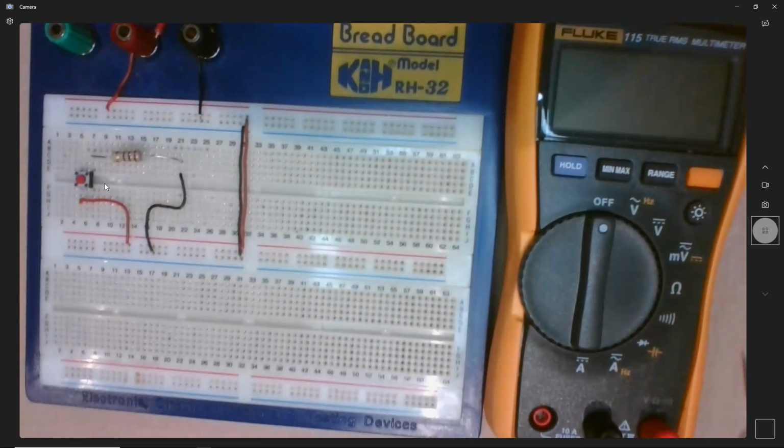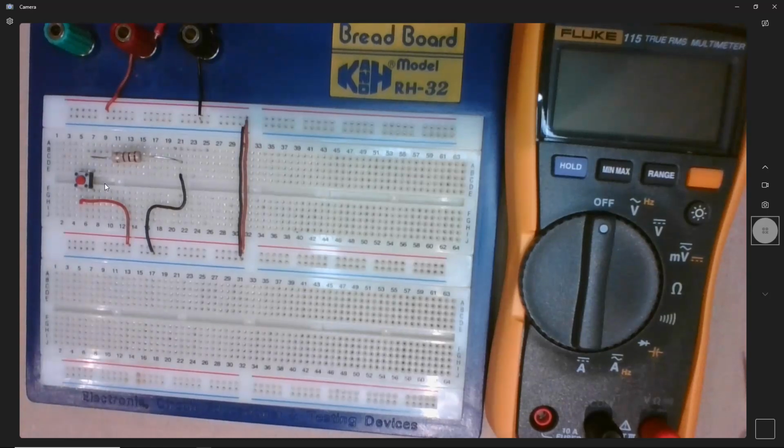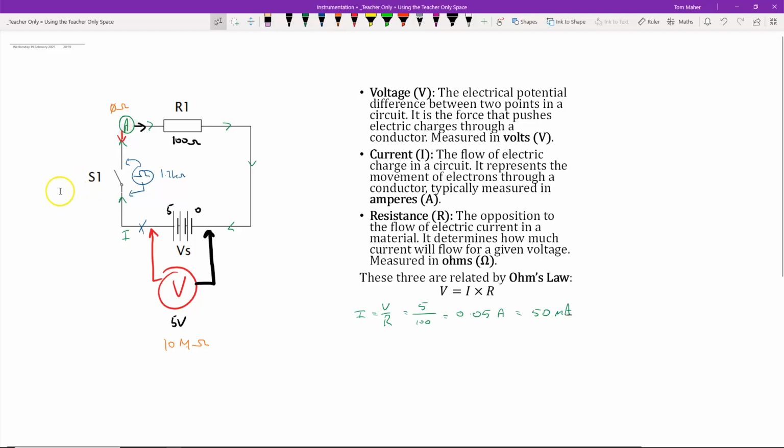As I said, it's very important to move that lead back because, let me go back to this one here for a second. With the meter at 0 ohms, when we were measuring current, if we leave the leads in that position and then I switch back to voltage, when I go to measure the voltage here, my meter actually is 0 ohms.